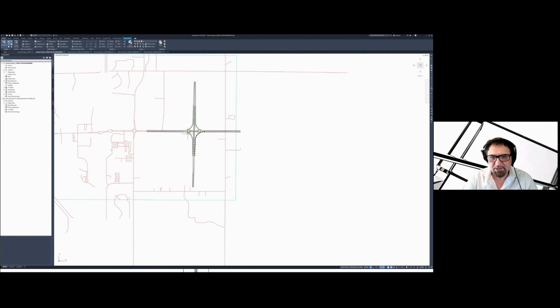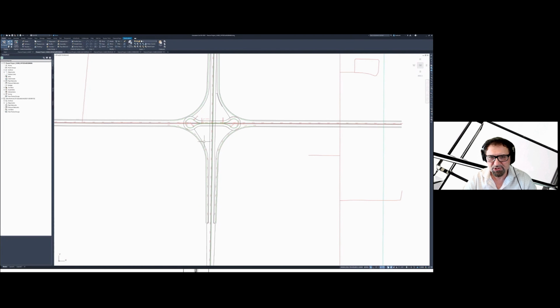All right, so as you can appreciate, this is a fairly complex interchange. I'm just going to show you the number of alignments there. So the centerline alignments, not even going to existing, there are a few hundred of them over there. So here, from the two centerline alignments, I've also designed rotary. Let's select it: rotary north and rotary south. They are two rotary alignments derived from those circles, and I also have offset alignments created from each one of them. As I said, offset alignments are easy to create.